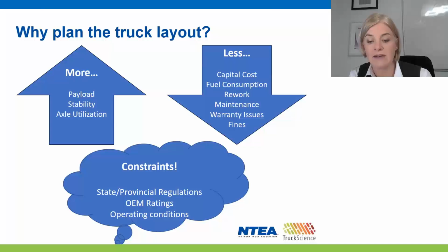Secondly, the capabilities of the chassis, for example, the gross axle weight ratings and gross vehicle weight rating. And lastly, we need to take into consideration the operating conditions, for example, the space available for the vehicle to turn. No doubt you could add to this list.